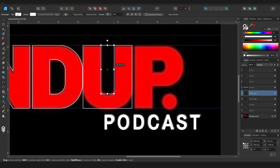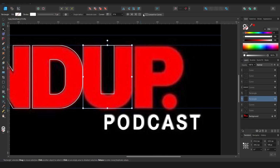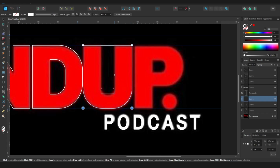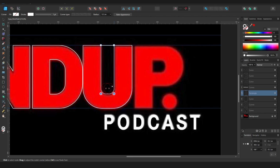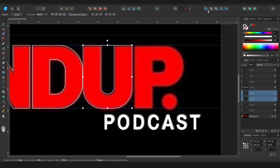And then hold Control, scale it in like that. Grab this bottom one, hit the A key. Hold on, A key, select, convert to curves, grab these two corners, hit C, and just kind of round that out. Same thing here, grab this, round that out. And then we can take these two shapes, hit the V key, and then we can subtract.